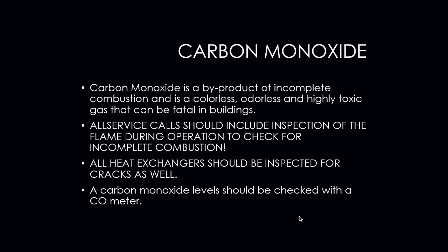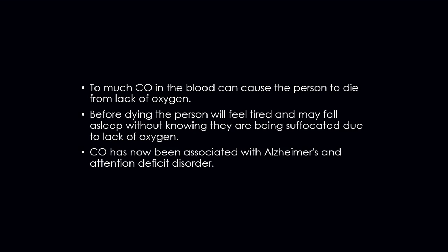Okay, because the heat exchanger is the only defining piece of equipment inside a furnace that divides between life and death. We need to be inspecting that to make sure that it is intact. A carbon monoxide detector, you should have those as well if you have the ability to have one. You should be taking a carbon monoxide reading in a home just to get a baseline of what is going on. Too much carbon monoxide in the blood can cause that person to die due to the lack of oxygen. Before dying, that person is going to feel tired and may fall asleep without knowing they are being suffocated due to the lack of oxygen. Okay, CO has also been known to be associated with Alzheimer's and attention deficit disorder.